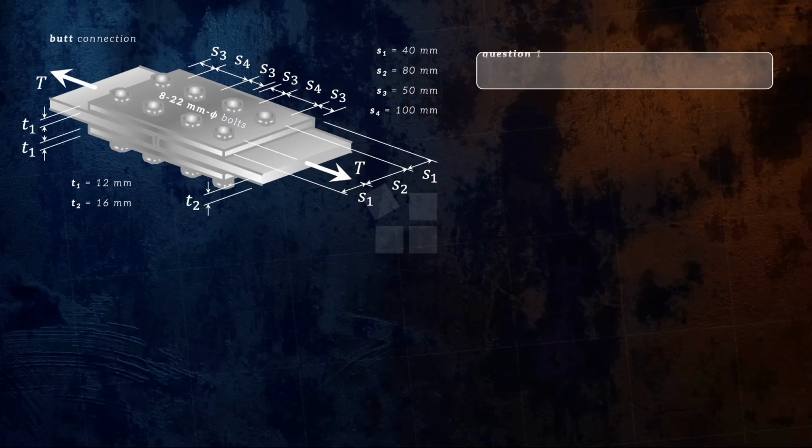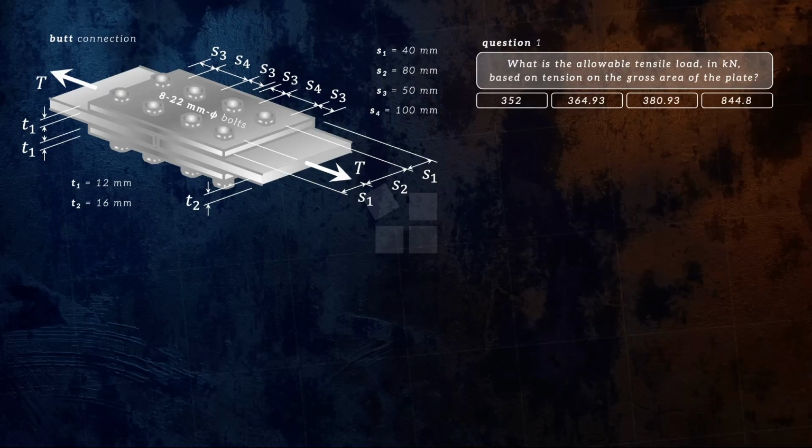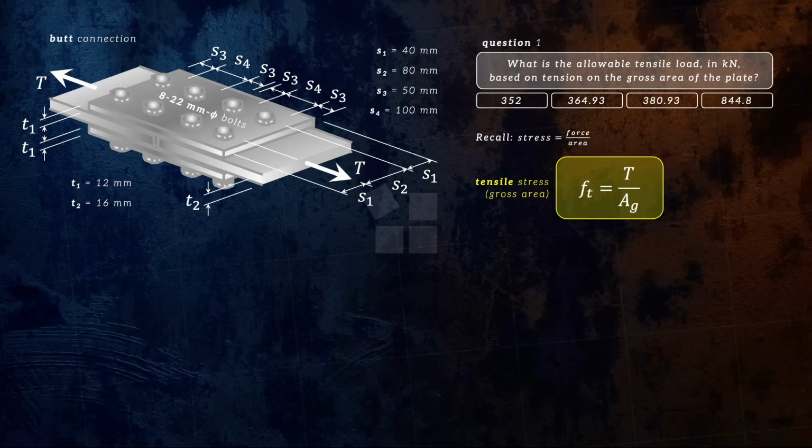For the first question, we are asked to determine the allowable tensile load based on tension on the gross area of the plate. Let us recall the concept or formula: stress is equal to force over area, because from this concept came the formula we are going to use to solve this particular question.